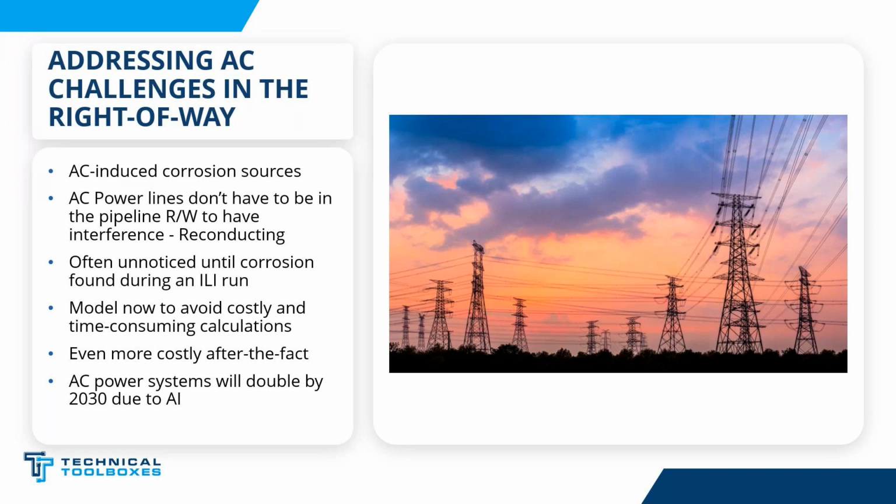Well, we give you some default information, and we even give you some factors to get the peak current. With our software, you could use a factor of 3 for the default to get a peak current to get started. So you don't have to wait until a power company gives you the information. You don't have to count the number of discs on the insulators and all that other stuff.